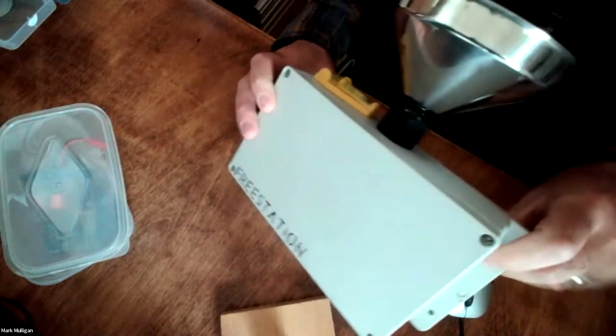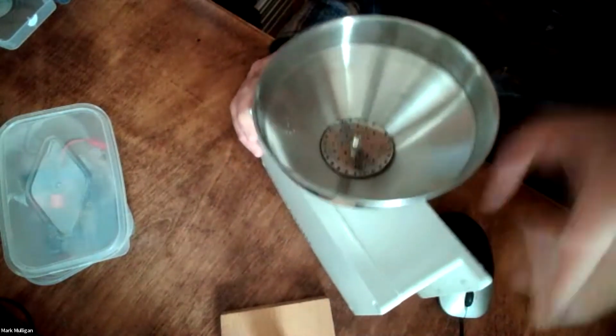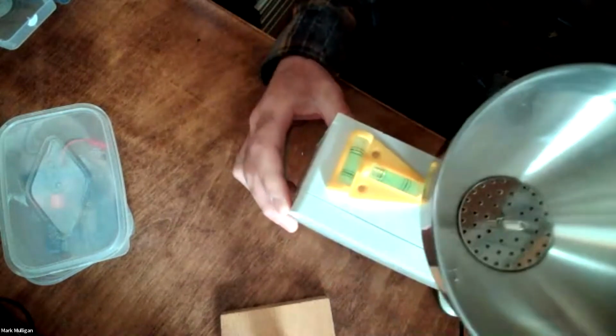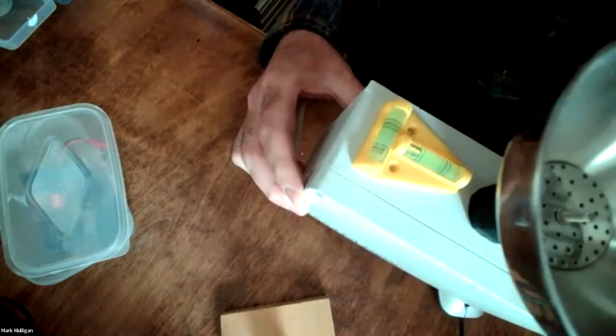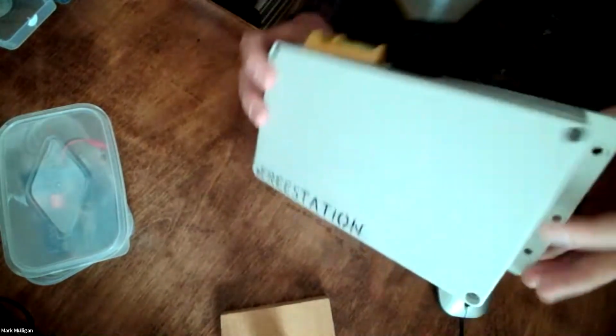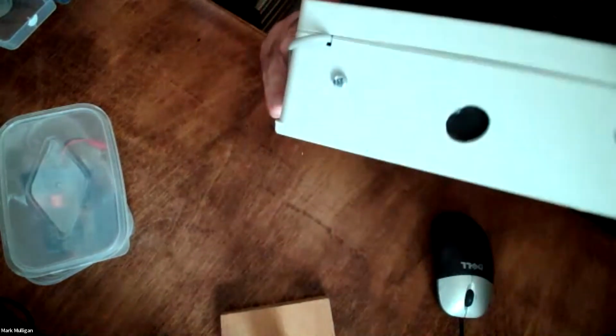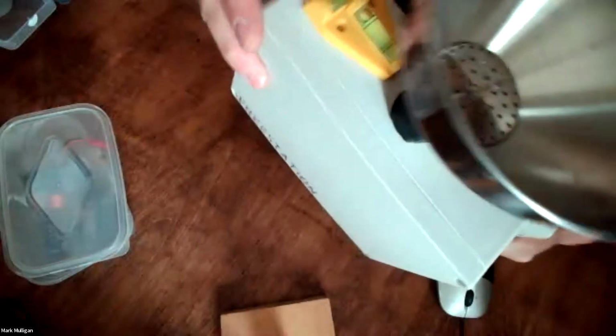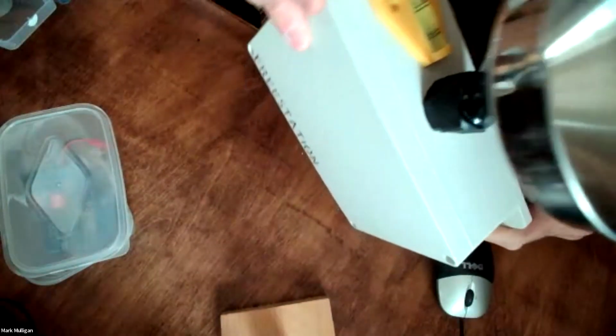So we enclose it in a box like this, and we put a proper funnel on it with a spirit level, and we protect it from insects and other things with mesh underneath, but it still drains, and that works very well. Gives us instantaneous rates of rainfall as well as accumulating rainfall at the logging interval of the sensor.